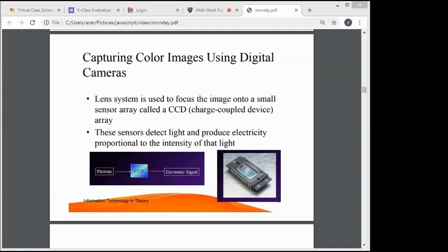It can measure the electrons from each picture element as a voltage. A CCD chip replaces the silver halide film which we use in analog cameras. So using a CCD, there is no wet chemistry processing in the darkroom, and the image is available for immediate feedback.